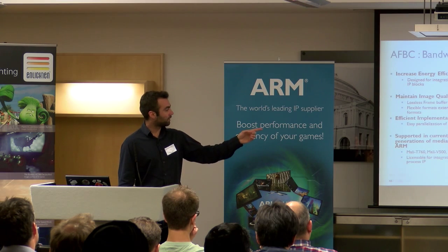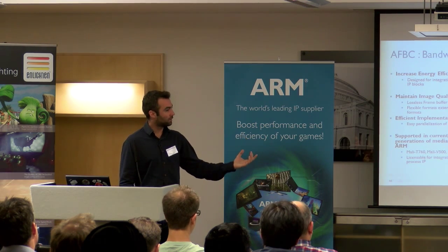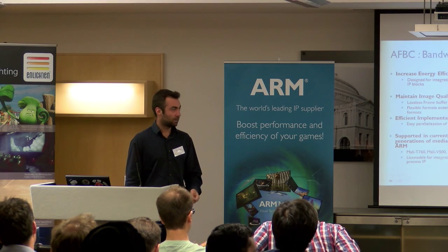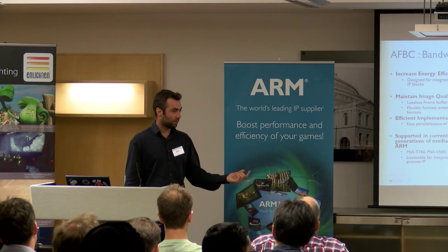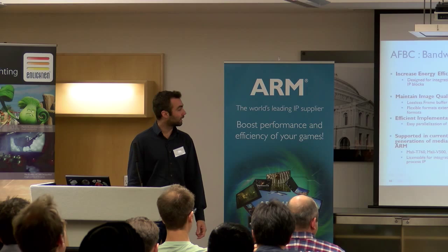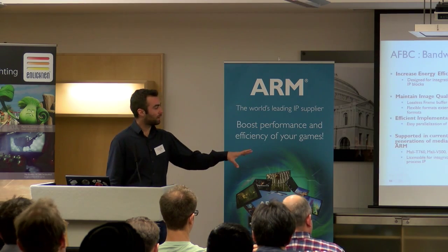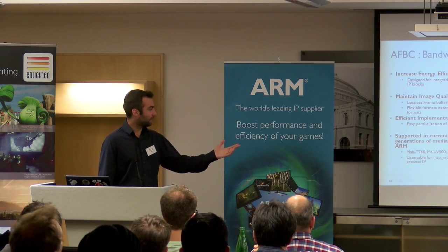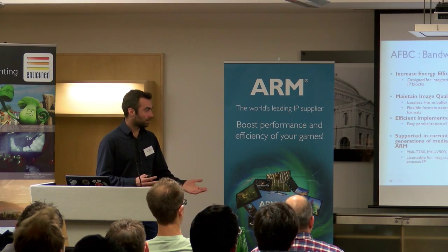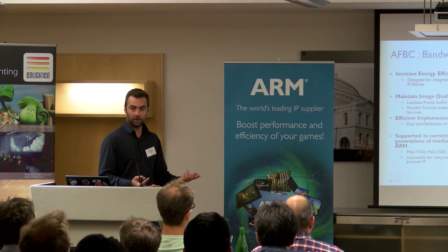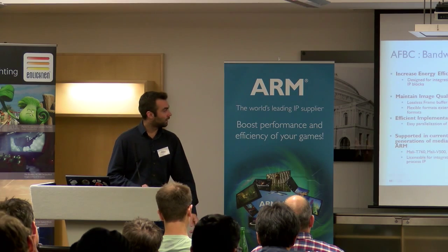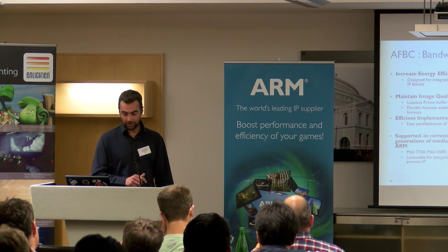So for example, T-Rex is having this very low compression rate just because it's having lots of vertex complexity, and only a small proportion of the bandwidth is attributed to buffers, which can be frame buffers that can be compressed. While other more balanced benchmarks like Manhattan or even real applications like Angry Birds are having a better vertex to pixel complexity ratio, and you can achieve much better compression for the overall application.